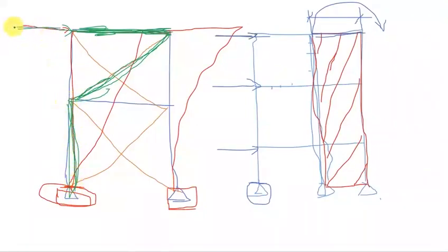Very interesting. Load comes from here, travels through this, and will be resisted by this, which will be in tension, and at this point, this load will just travel to the foundation. So if you're designing this member here, make sure that it can take this load, right? But it is good to do your analysis.